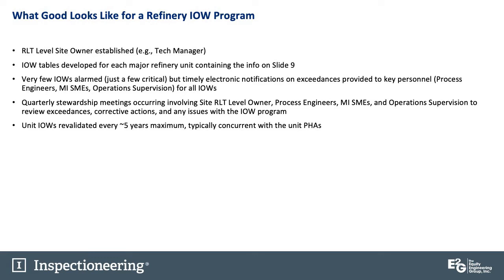You have IOW tables developed for each major refinery unit containing the info I showed on that previous slide as a minimum. You want very few IOWs alarmed, just a few critical. I don't think you need to set yourself up for a lot of alarm overload with these programs, but you do want timely electronic notifications provided to your key personnel. Again, this can and probably should be a very small group of key personnel for minor exceedances, expanding to maybe additional personnel when the exceedance is fairly dramatic and needs some more rushed action to correct.